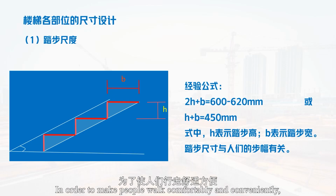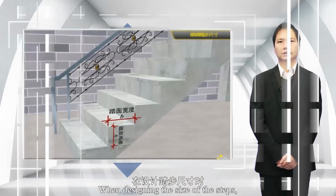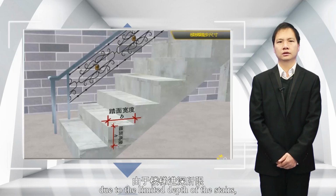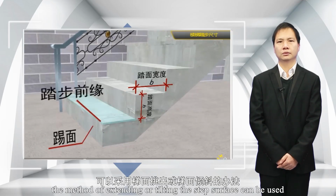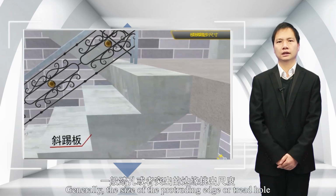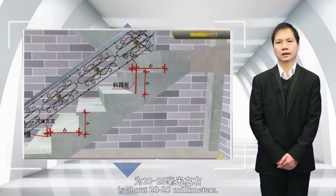In order to make people walk comfortably and conveniently, the size of the steps should be coordinated with the size of their stride. When designing the size of the steps, due to the limited depth of the stairs, when the step width is small, the method of extending or tilting the step surface can be used to increase the step width. Generally, the size of the protruding edge or tread hole is about 20 to 25 millimeters.